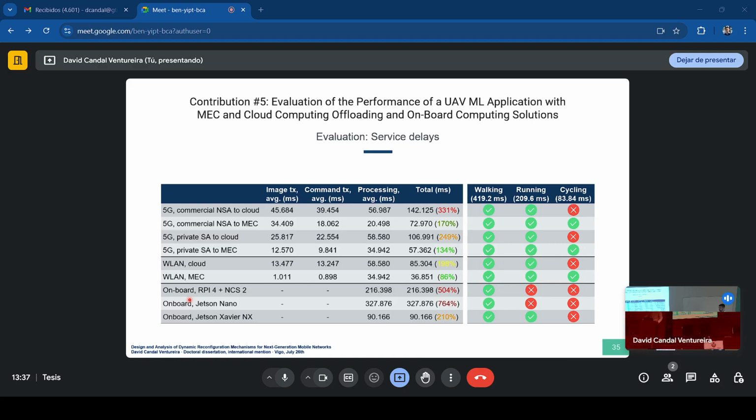The difference in flight time, compared to when you just use the Raspberry for offloading, the highest difference was just 3% in the drone, with this board, which was the one that performed better. This is because the drone motors consume a lot. We may have, for example, another vehicle that has a limited battery, and therefore it will have a higher impact on battery life.